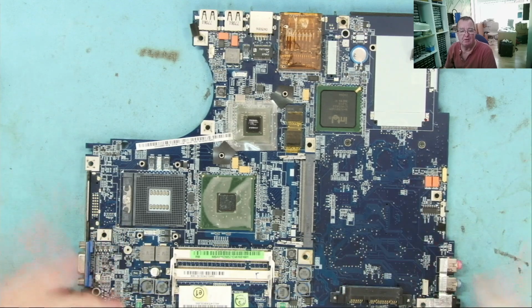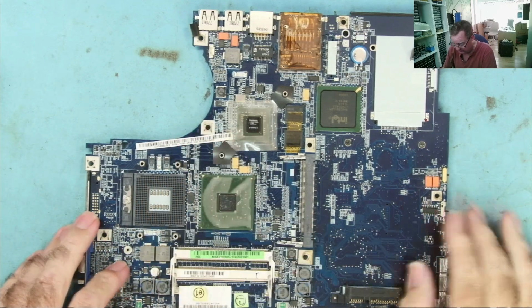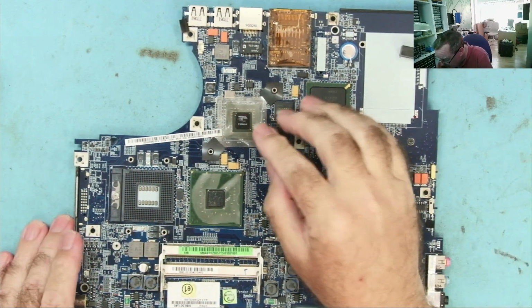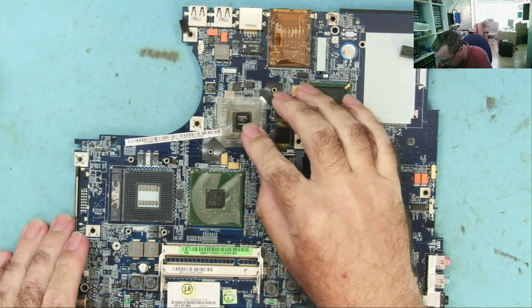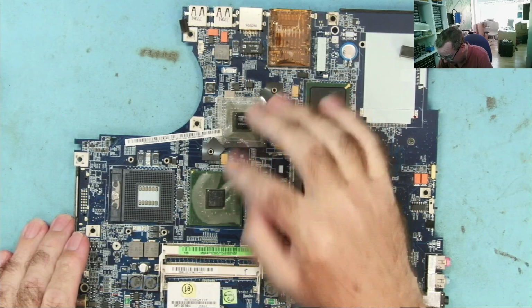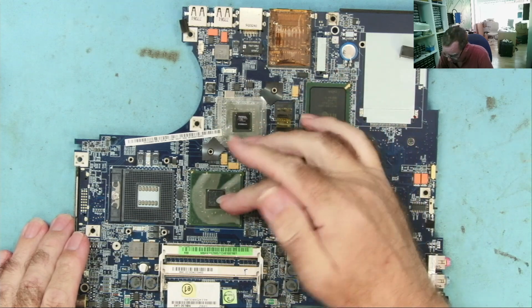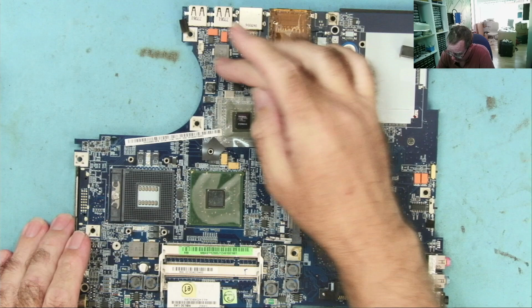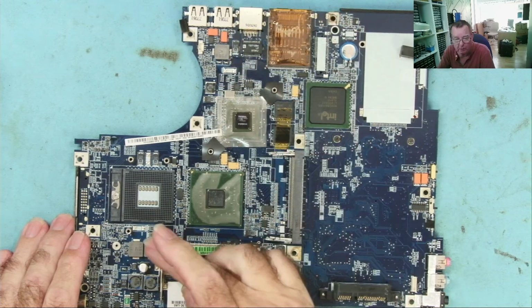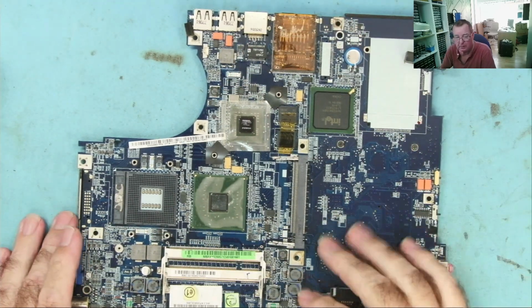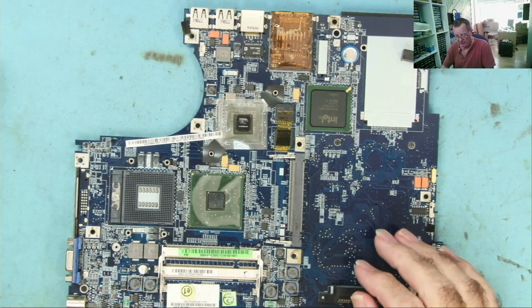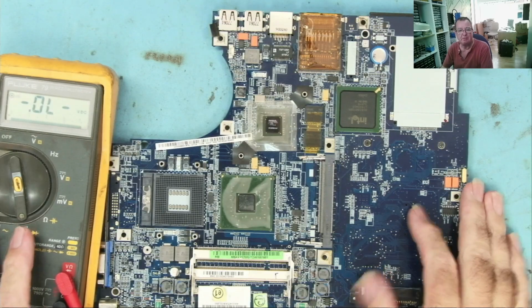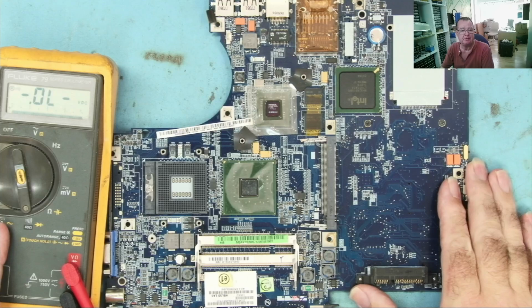Here is an old laptop board. This had a processor in a socket. It's not a modern one, but it has an onboard GPU here, NVIDIA. It has a Northbridge or PCH here. And these will be powered from these various inductor coils. This one, these, and so on. More of them here. Now, if we go to diode mode and we look around this board, let's see what we find.